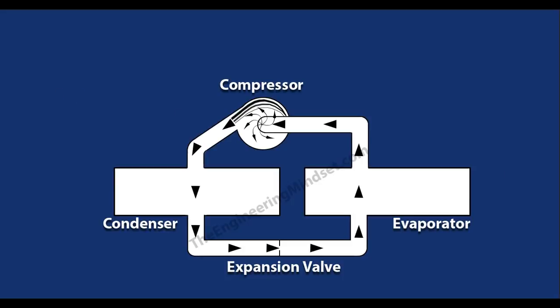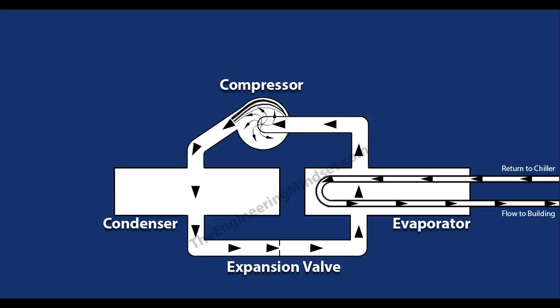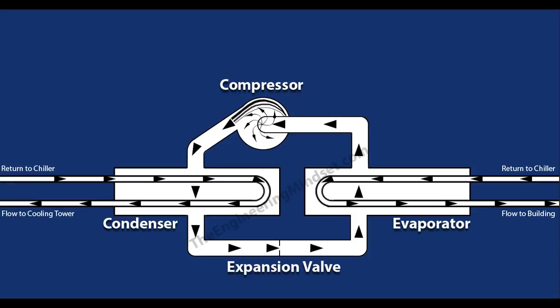to the cooling towers. The secondary circuit you need to know about is the chilled water loop, and this is the heat from the building that's being collected, sent to the chiller and then back to the building. The third and final circuit that you need to know about is the condenser circuit. This is the heat which is being sent to the cooling towers and coming back to pick up more heat. So these are the four components, these are the three circuits.